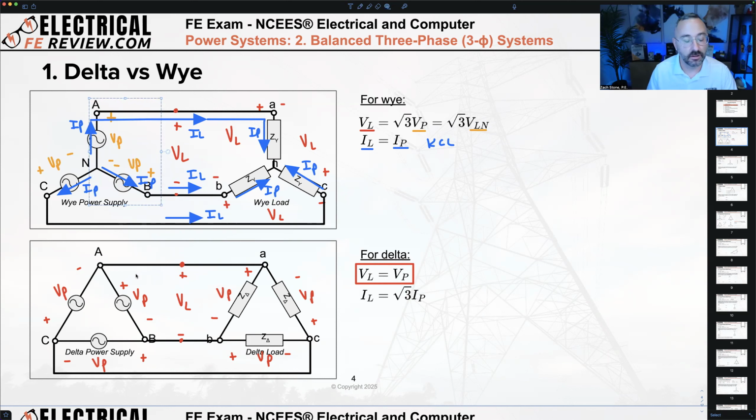But now, when we look at our delta connection, look, my line voltage from the A phase conductor to the B phase conductor down here, is it equal to the voltage across just my A phase? Yeah, it sure is, right? Essentially, these voltages are in parallel. If I put a positive voltage polarity terminal here for a voltmeter, it's no different than if I put it right on this A terminal or even right down here.